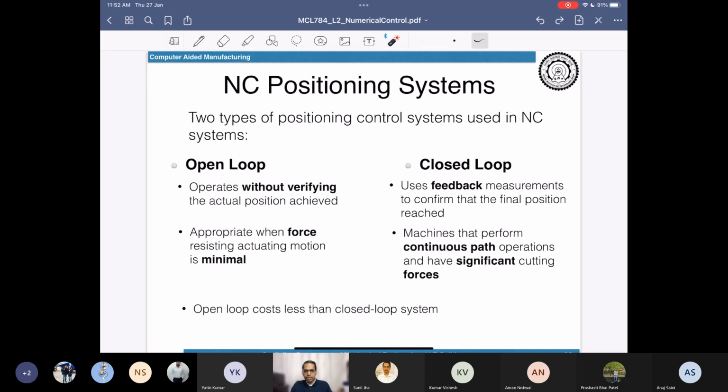You can easily correlate that in a 3D printer there are no forces as such, only minimal forces to move the base platform or the hot bed against the extruder. That is how it is successful. Why invest in closed loop servo systems when you can easily perform those motions with a belt and pulley coupled with stepper motors?